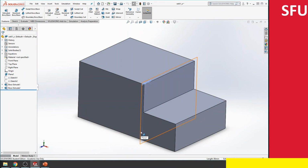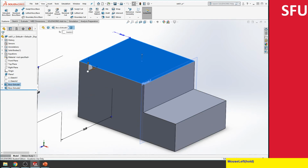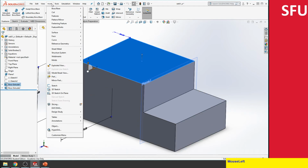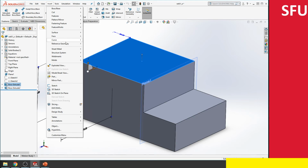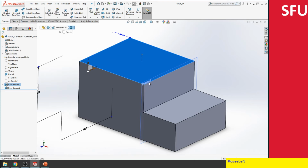So I've opened up this model already. Let's see if I can do a direct modeling of this face. I'm going to click on this face. If you remember, I said insert, and then you go to face. Here is where all of the other options are. For now, I'm not going to do any of those. Rather, there's actually dome and all of that stuff, and I encourage you to take a look. But here we're going to go to insert and then face, and then we're going to say move.